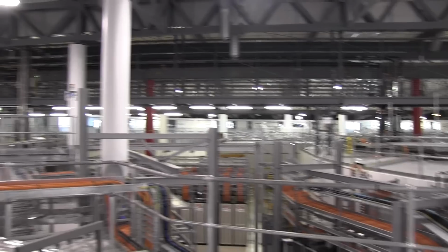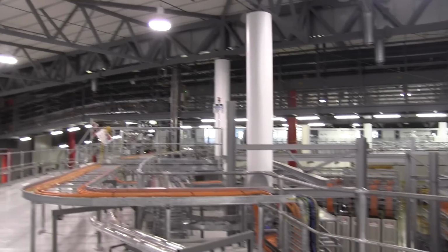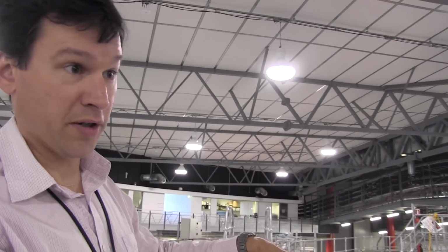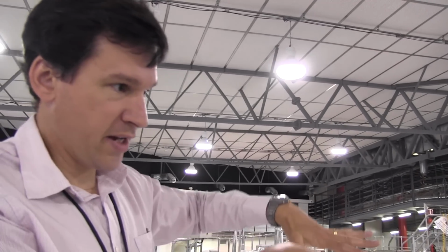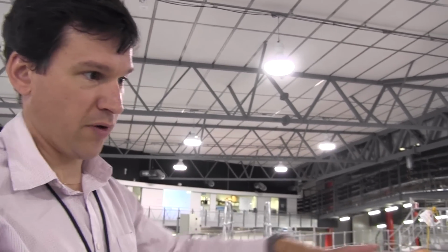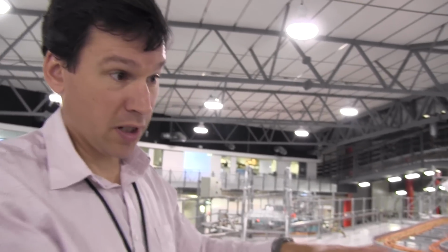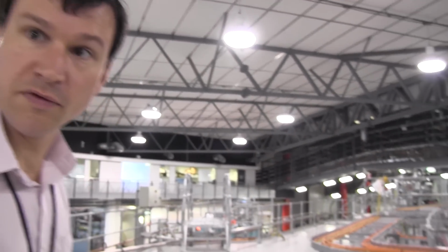And the concrete slab that the building is over the top of is not connected to anything. It's just floating on that clay bedding. And so as that dries and as that moves and slips around as much as it can, given the constraints of the pylons, we just readjust to that movement, but it's not directly coupled to any of the other structures, to isolate the floor vibration.